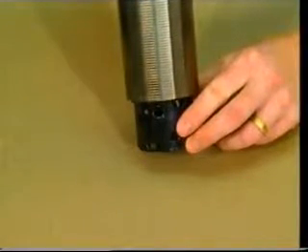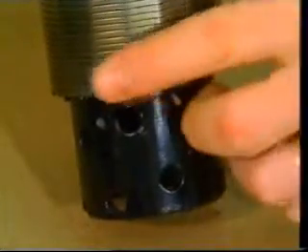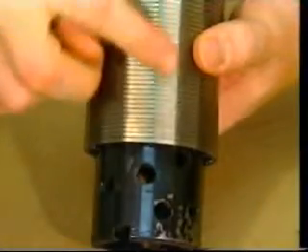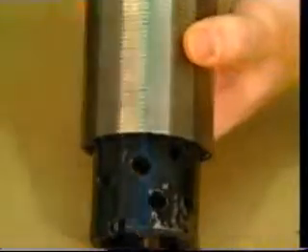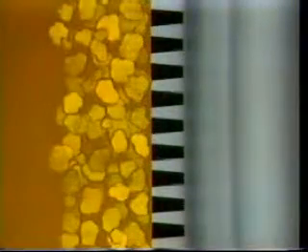0.006 inches is standard, and sizes as small as 0.003 inches are available, greater inflow area, special anti-corrosive construction, greater mechanical strength when mounted on perforated pipe, and a more pronounced undercut, which helps prevent plugging.